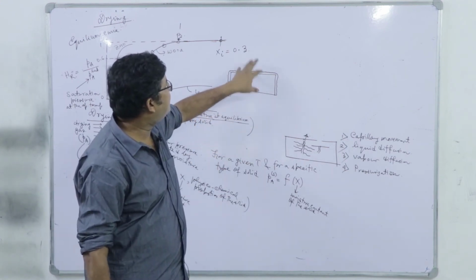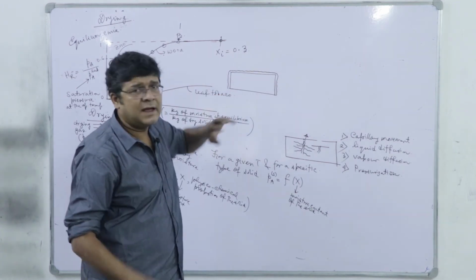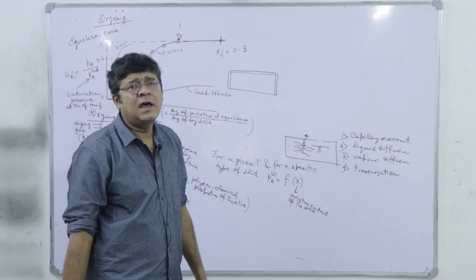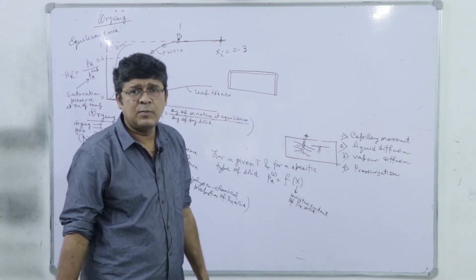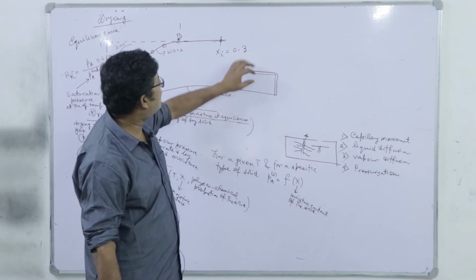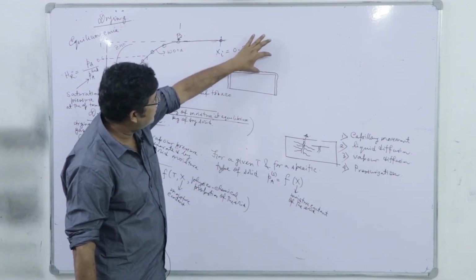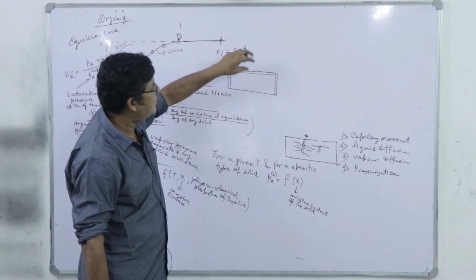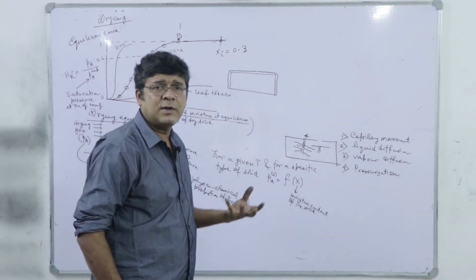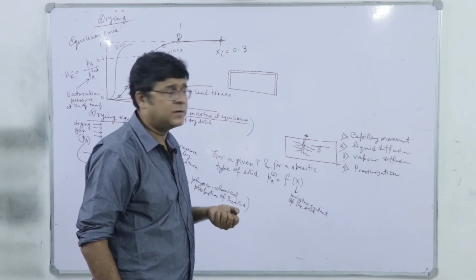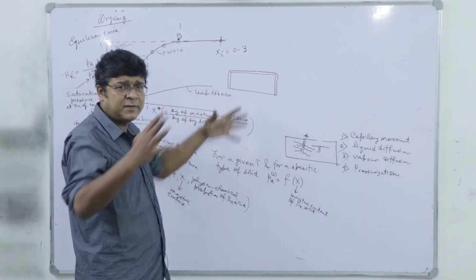So, this electric force and the double layer force, that scale is in the order of nanometer. It vanishes completely at around 10 nanometer, right, for most of the surfaces. So, what will happen is that the liquid here, whenever we are having an external film, it is not having any physicochemical interactions with the wood fibers, right, there is no intermolecular forces. So, it is rather free.